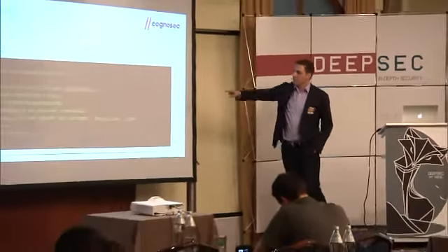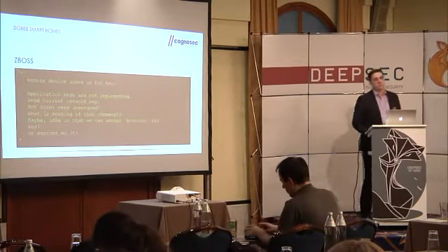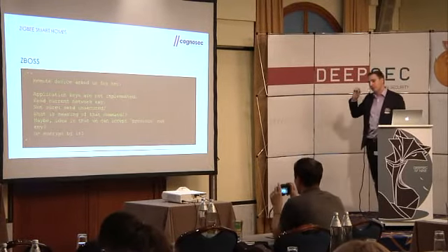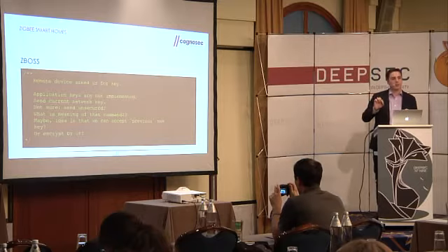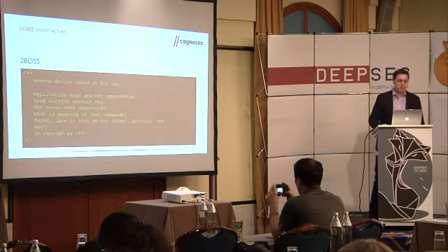Back to the first comment, it's also really interesting that application keys are not implemented. This means the security level is only based on the network key, and there are no device-to-device keys possible using this version of the ZigBee open source stack.